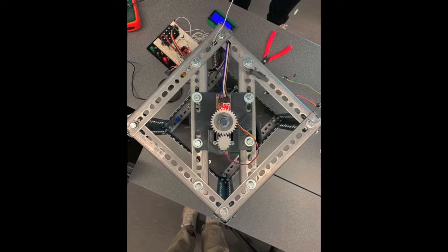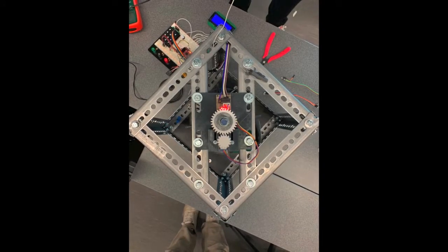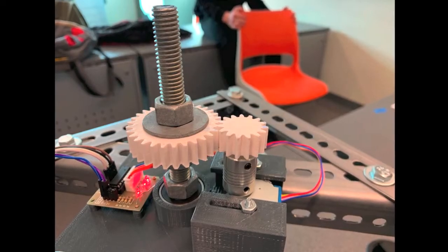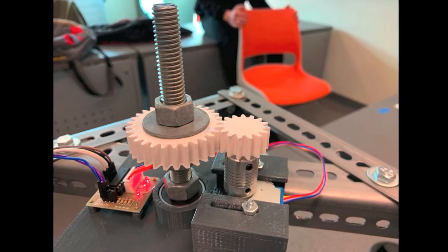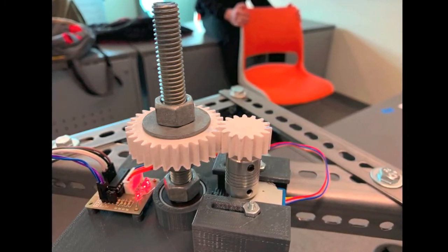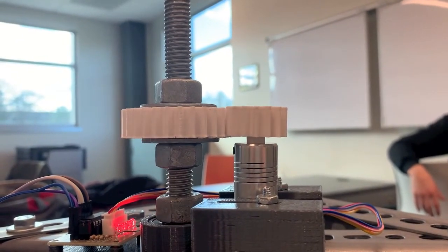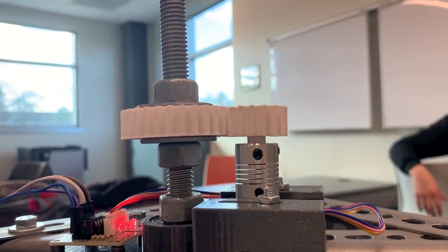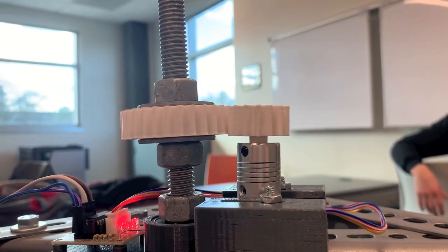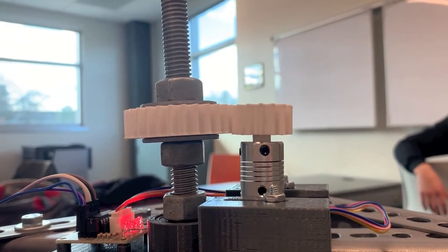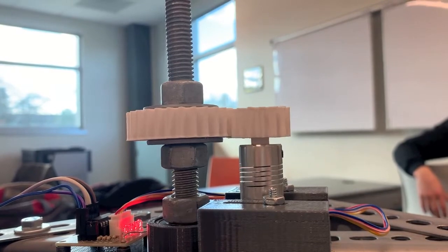The bearing shaft fit proved to be crucial. In the close-up of the gear train function, you can see the run-out induced in the shaft due to a poor fit. We will address the fit in a future machine to ensure the gear train has reliable support. We also were able to see what kinds of gears printed well within the precision of the 3D printers. The frame ended up being strong, but there were a few issues with straightness and warping that will be accounted for in the next version.